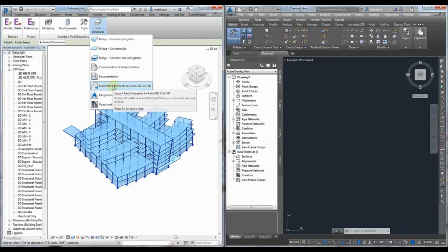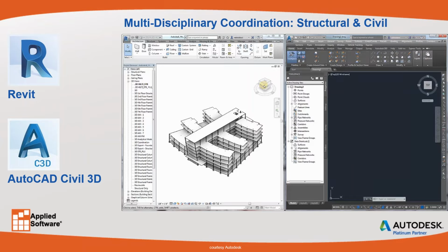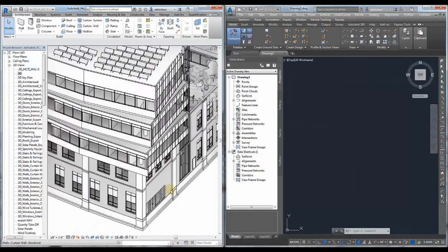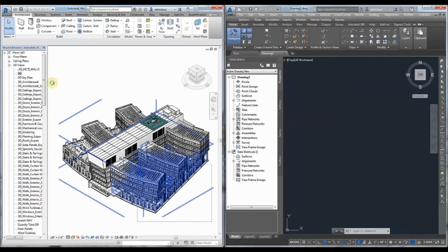So if you haven't done this before, the origin point in Revit can be relocated to any location on the site, and I would recommend putting this somewhere on the property line of the site. There's very few areas of the project that don't change during the course of the project. One of them is the property line. So if you had a property line for the site, this is where I would recommend placing that model origin. You could just coordinate that with the civil engineer.